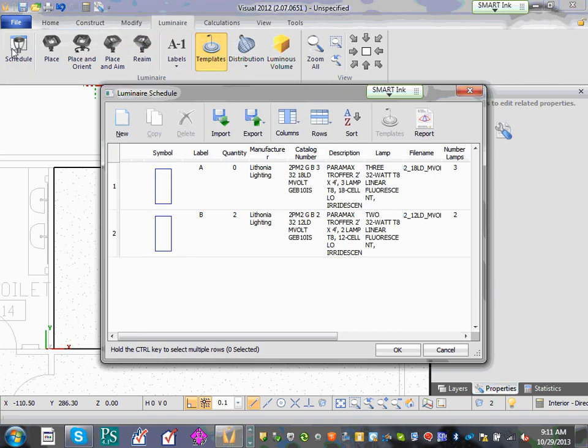I don't know if it'd be easier for you. What I would do is maybe just go through my whole list and build this schedule first to make it go faster. You build it once, then you're done. I don't know if it's the same for all your other projects. We're using LEDs next project, so it's not the same, but if you have a project that has the same kind of schedule, you can export the schedule and import it every time. Say you're on a job and you're using the same stuff. You can have like schedule ABC, and you can just import it in, then it saves you quite a bit of time. So for this one, we'll just do, this is a mechanical room.